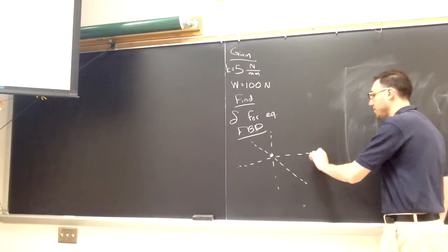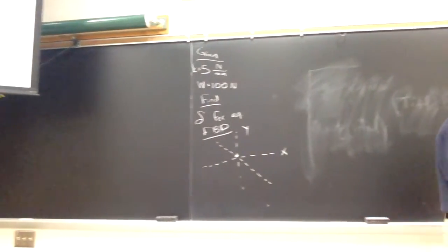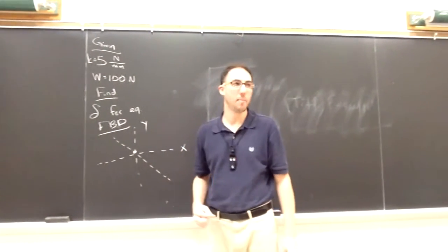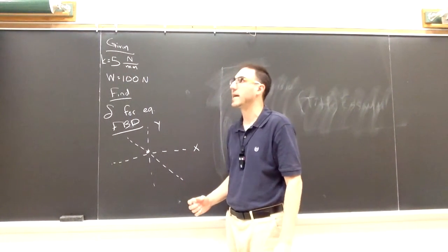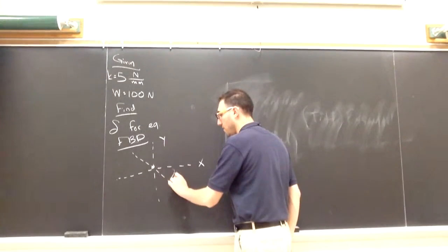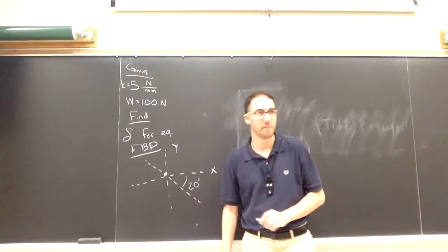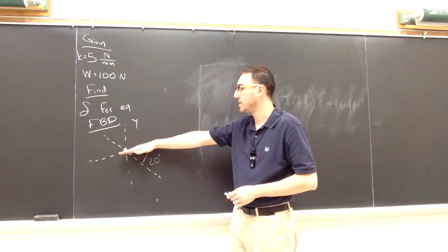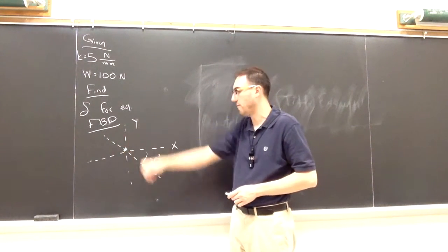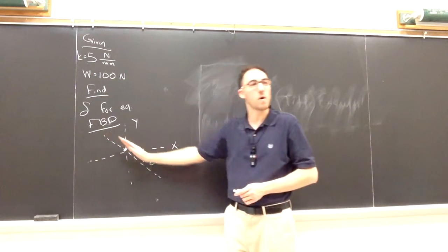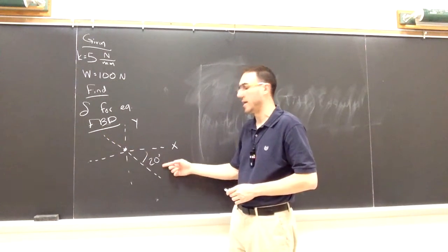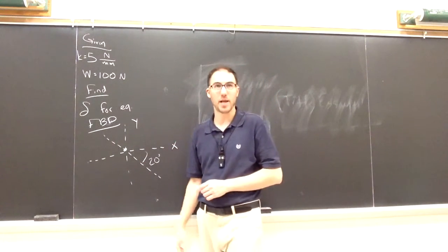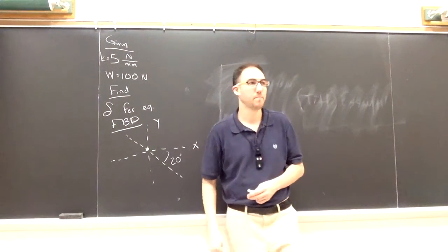All right, so I think it matches my notes here. I stuck with an XY coordinate system, X right, Y up. Although in this case, because we're at a slant here, it actually might be useful to use a rotated coordinate system, but I'm not going to get into that right now. So as far as construction lines, X is horizontal, Y is vertical. But because we have an incline here, I'm adding another construction line that's going to be 20 degrees down from X. And we'll see why this will be useful in a minute.